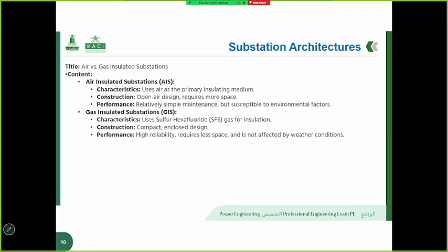So in a GIS, all key components such as bus bars, circuit breakers, and disconnectors are enclosed in sealed gas-filled metal tanks. This compact design allows for a much smaller footprint, often requiring only 10% of the space needed for a comparable AIS. This makes GIS an ideal solution for urban environments, underground installations, or areas with limited space.